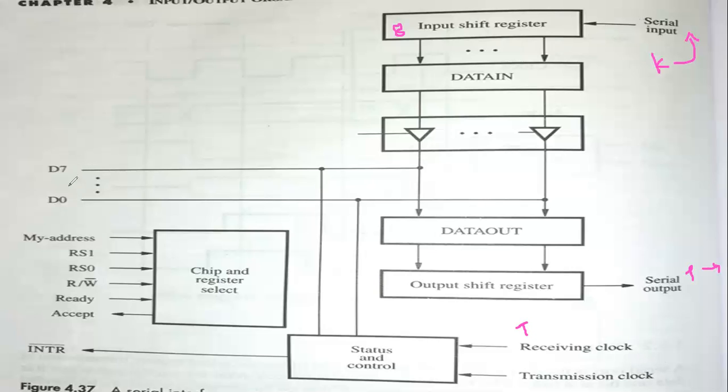Now feel that the output device, a printer, is ready to print the content. So it will raise a request towards the devices using this status section. Later the data to be printed will be uploaded in the data line. Here the data is available, but it is not yet uploaded to the data out. When we raise this slave ready, only then can we upload, remember. Now the address for this particular device will be uploaded, then the write command, then the ready signal.